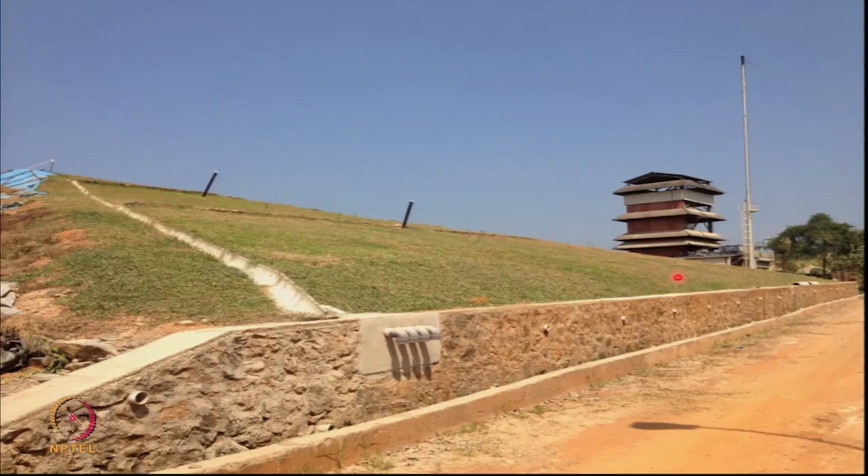This is yet another landfill, grassy slope. You can see this drain. This is the stormwater drain. Stormwater drain at the toe. These are the berms which have drains in it. Those berms allow the water to flow through this, and this is all segmented, prefabricated units. Why? Because the surface may settle. So you allow the water, it comes out to this and is carried away.